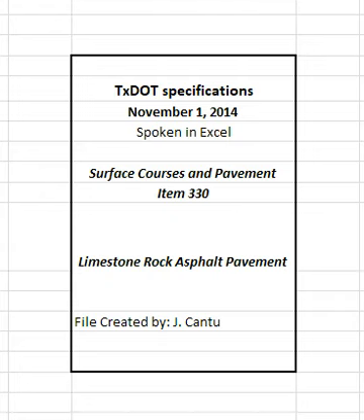Process to balance production, delivery, paving, and compaction to achieve continuous placement operations. Paver operations, for example operation of wings and height of mixture in auger chamber, to avoid physical and thermal segregation and other surface irregularities, and procedures to construct quality longitudinal and transverse joints.